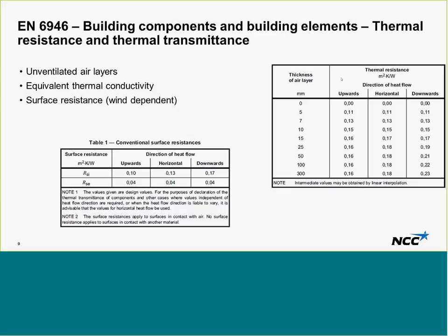One nice thing here is they have a little bit of a table with thicknesses of air layers where you can have thermal resistance of this air layer. That can be good to put into calculation if you need to. Generally, we try and avoid air layers. If we have a ventilated facade, for example, in Sweden, we generally just put the RSE is equal to the RSI, and then we don't bother simulating the brick, for example, a ventilated brick.